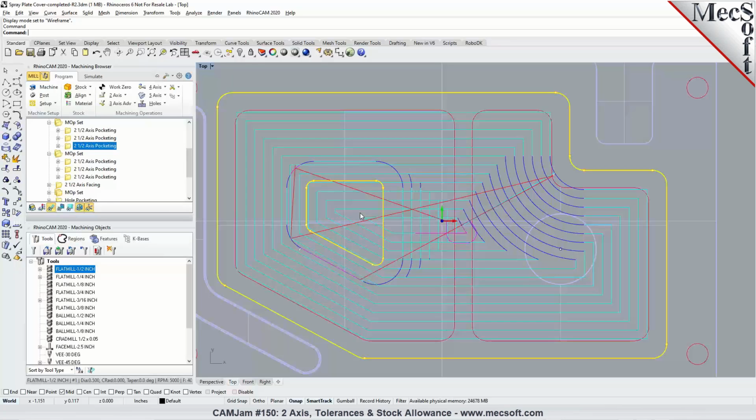I want to jump in here, Uday, and talk a little bit about tolerance stacking. You mentioned that, but I want to dive a little deeper. When we do arc fitting, we are actually fitting arcs to the toolpath points. We are looking at just the toolpath and fitting the arc geometry to it. Obviously, when we do that, we have to use a particular tolerance, and this tolerance is independent of your machining tolerance.